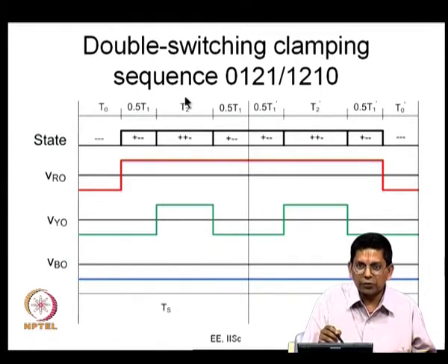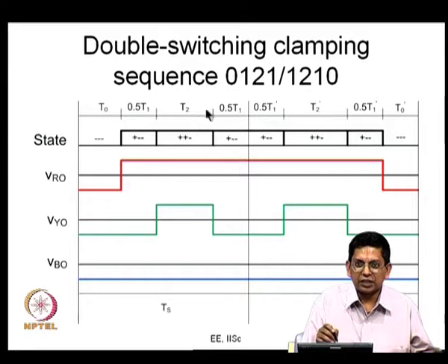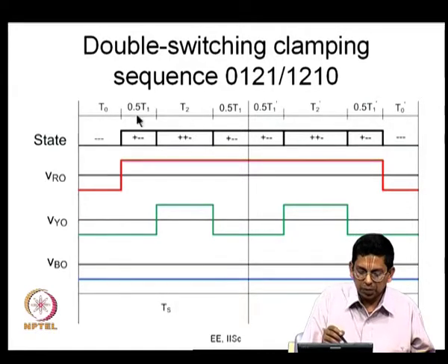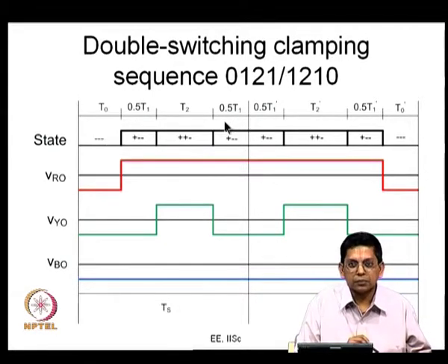Active vector 2 is applied for T2 seconds as determined by calculations; we have an expression, T2 is Vref sin alpha by Vdc sin 60 multiplied by Ts, and so on. Similarly, you have the required T1. That T1 we are not applying in one go; we are applying active state 1 twice. We are going from 0 to 1, 2 and back to 1.